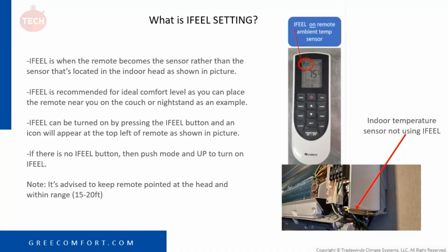if it's not I Feel, the bottom right picture, that is your indoor ambient sensor that is going to be in the indoor head. That is what senses temperature if you're not using I Feel. So I'm going to say for optimal comfort, I would recommend using I Feel.